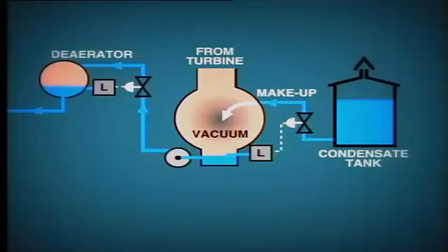When load is increased, the opposite situation takes place as the boiler water level increases due to swell. In this case, the boiler feedwater control valve reduces flow, the de-aerator level tends to rise, so decreasing the de-aerator control valve opening. This causes the hot well level to rise, thus causing the makeup valve to close completely.